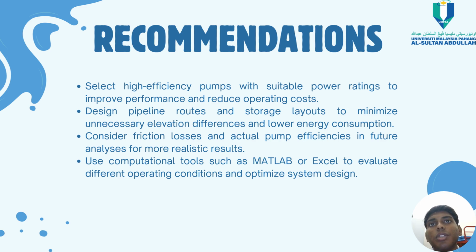Based on our mini project, we recommend selecting an efficient pump with appropriate power rating to improve performance and reduce operational costs. In addition, pipeline and storage system layout should be designed to minimize unnecessary elevation difference whenever possible. Future studies should also include factors such as friction loss and actual pump efficiency to obtain results that are closer to real industrial conditions.